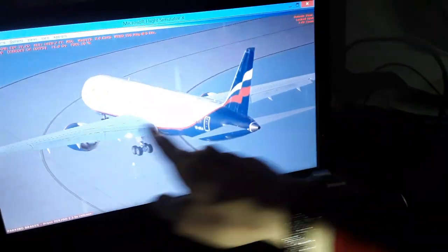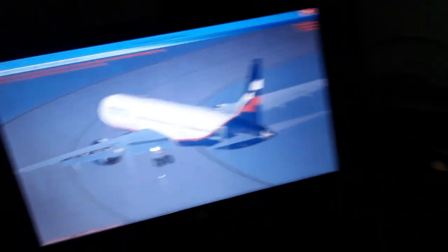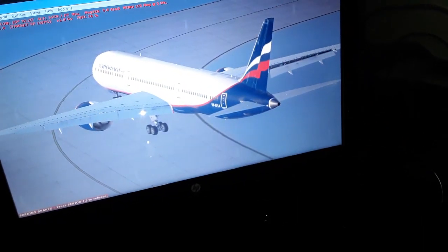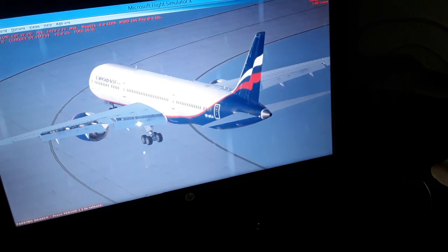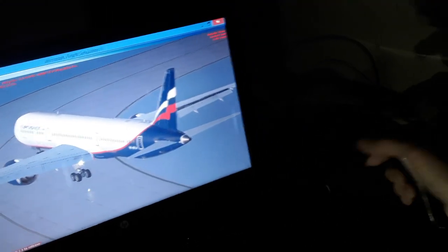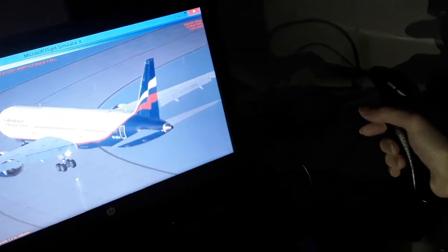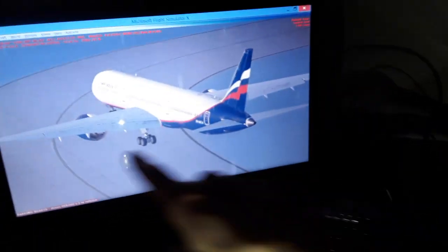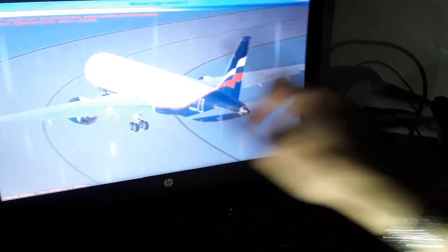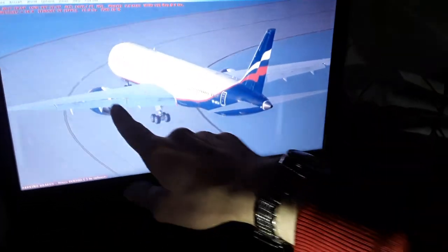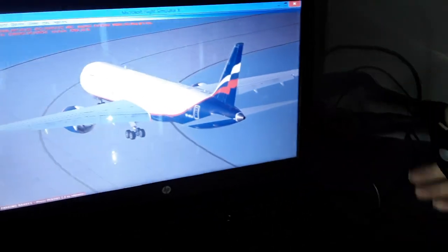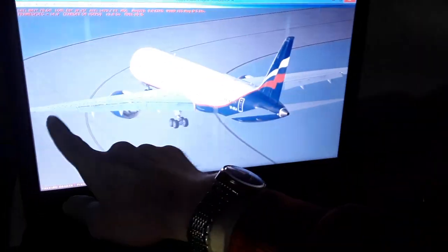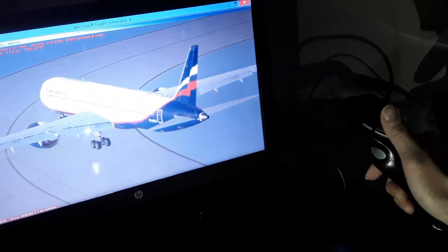Like this, so you create aerodynamic lift difference between the left and the right wing, more lift in the one wing, less lift in the other, so you make a turn in the air, you roll. And also in the side stick left and right in the Airbus you have ailerons and spoilers. In the Boeing also you have one more surface, you can see the flaperons here and here. So you have the ailerons here, the spoilers, air spoilers and flaperons in the Boeing.